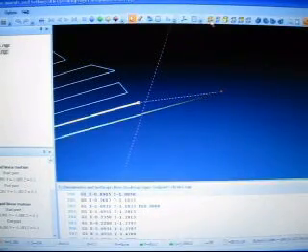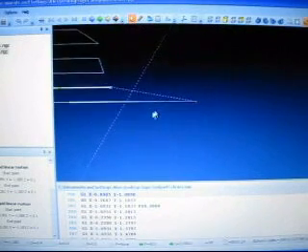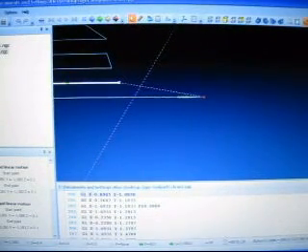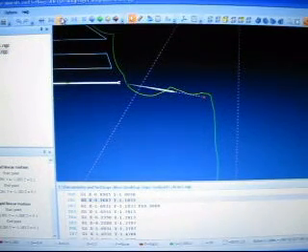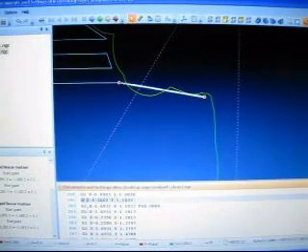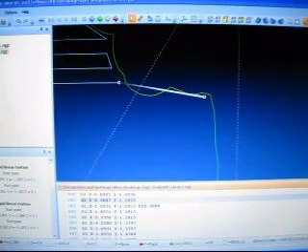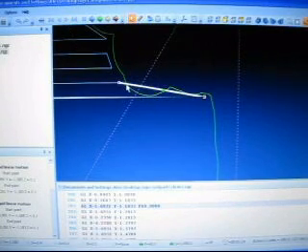Okay, so now I'm going to jump back to my top view, zoom in on this so you can see, and then I'm going to enable the clean cut. So now if you notice, that's going to be my feed, and right now it's set to a G0, but I'm going to change it to a G1. Alright, so it's a feed command. That would feed directly through my part.